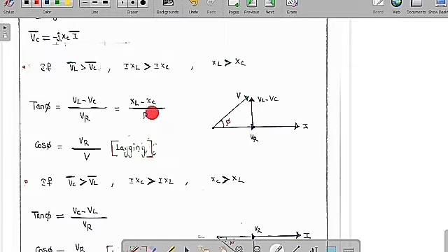If you want to know tan phi, which is opposite by adjacent, it is VL minus Vc by VR. As VL is equal to I into XL, Vc is equal to I into Xc and VR is equal to I into R, I is a common part, and we get XL minus Xc by R. Similarly, the cos phi power factor of this circuit is adjacent by hypotenuse, which is VR by V. So this is a lagging network, because the current lags the supply voltage.